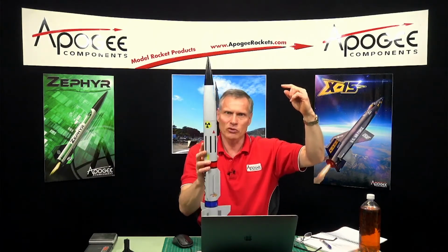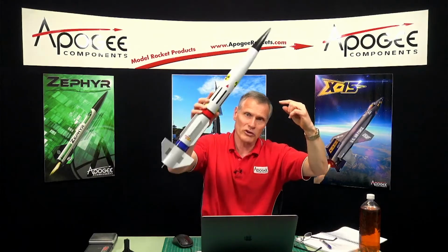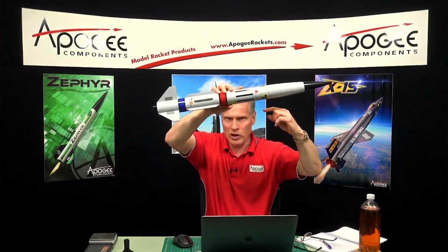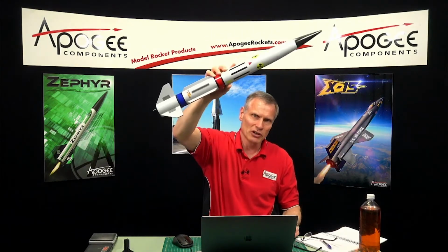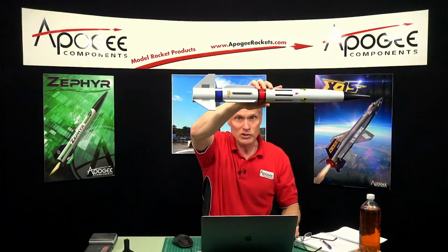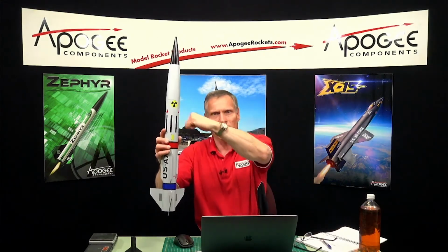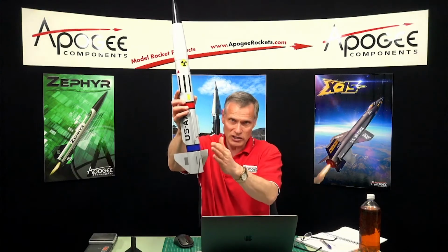And the rocket is going to want to weathercock into the wind. It always wants to zero out that wind angle of attack. So eventually, if we run the simulation long enough, it would be going horizontal so that it would have a zero wind angle of attack. But what happens is the rocket, as it's taking off, hits that wind, and it's kind of like thunking it. And it's thunking actually down here on the fins.